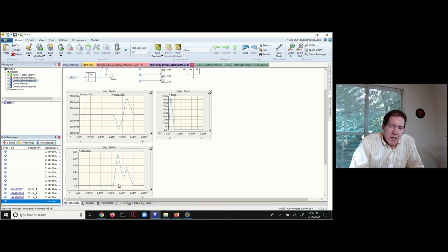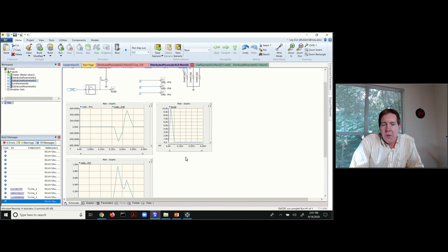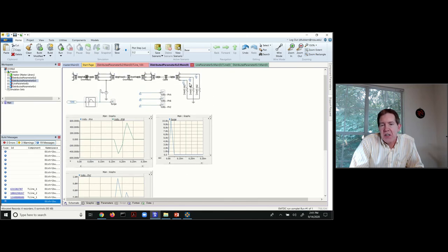Because if this voltage becomes too high or the rate of change is too high, then we could see some damage to the load, or maybe before it even gets to the load, when it hits the cable, this voltage could be such that we cause too much stress on the cable, and then it might actually cause some damage to the cable.